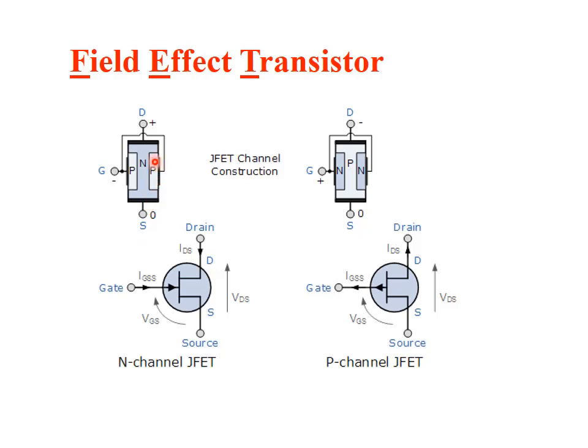As you can see, we have a semiconductor of, for example, an N-type, and this N-type semiconductor is doped with two P-type regions on the side, and these two are internally connected. On one side we have the drain, and on the other side the source, and here we have the gate. The transistor can be an N-type JFET transistor, or it can be a P-type. We call this path the channel. So the channel can be either a P or an N channel.